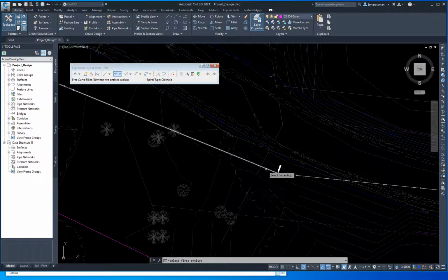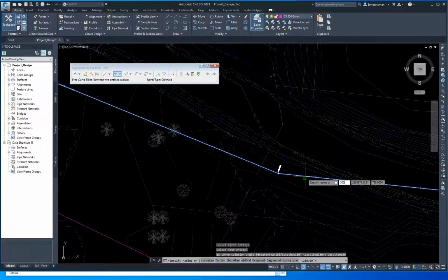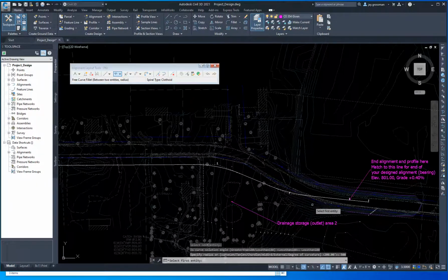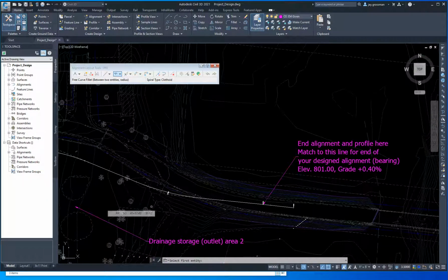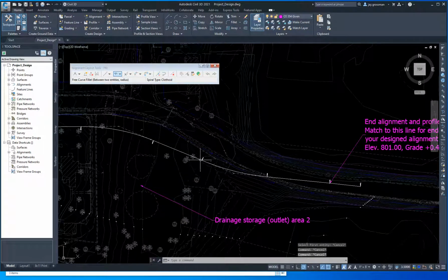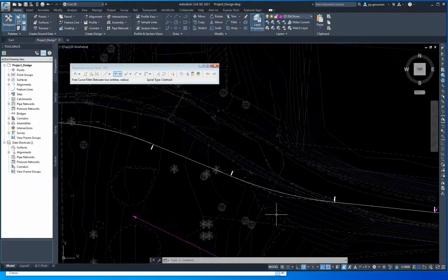And we got one down here, my last one, and less than 180. I'm going to put in a bigger curve here. Let's see what a big curve looks like. Oh, that's not that big. So there's a 500-foot, right? And then I'm done. And here's my end point right there. And I'm going to hit escape or the right mouse button to get back out of here. And now I'm back. I'm out of add curve mode and I'm in my general AutoCAD edit mode through here.